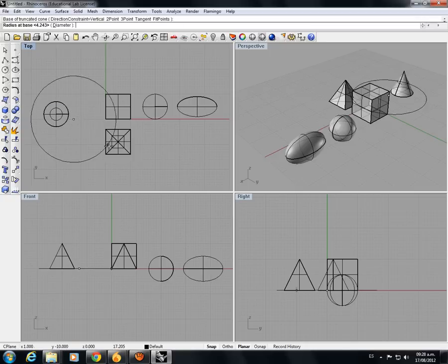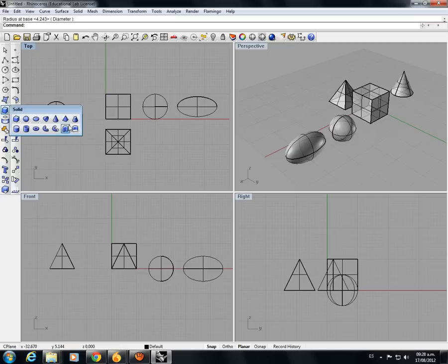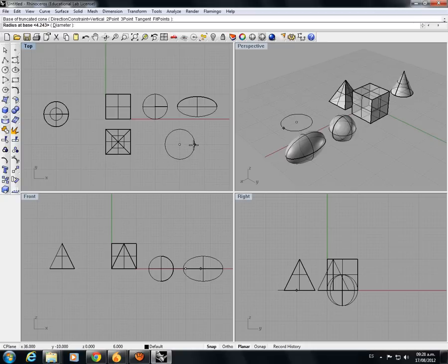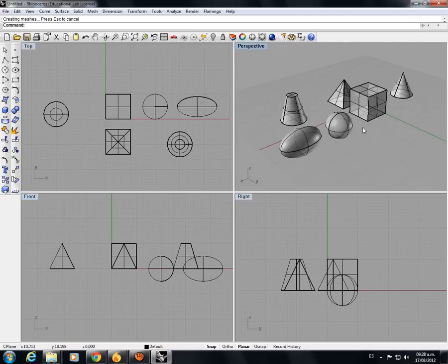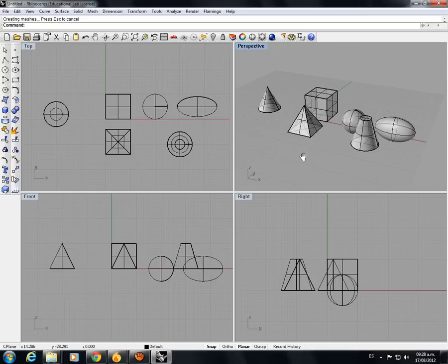We also have a truncated cone. Okay? We're going to create a truncated cone, and the truncated cone also works like a cone in the bottom, and then it's truncated on the top. So a 5 centimeter radius, and then on the top I can see how much I want it truncated. Okay, so that would be like the inner radius. The inner radius can be like this. Now the constructions of these shapes will help you create any object that you like, the combination of the shapes. Then the union of these shapes, or the Boolean difference of these shapes, will create a whole object. Okay, so we have these.